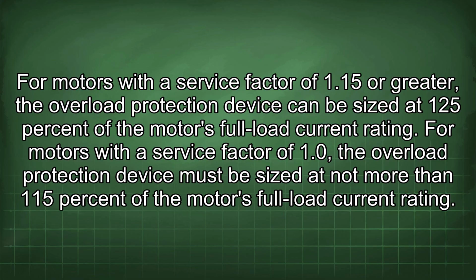For motors with a service factor of 1.0, the overload protection device must be sized at not more than 115% of the motor's full load current rating.